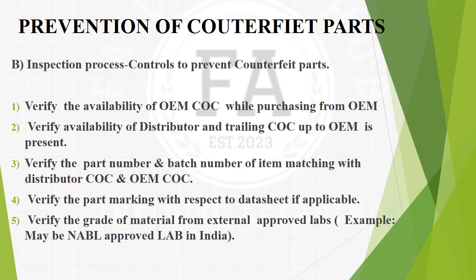So the incoming inspector shall verify the part number and batch number on the item packing, the part number and batch number on the distributor COC, and the part number and batch number on the OEM COC. So there shall be traceability between OEM COC, distributor COC and the actual part package.